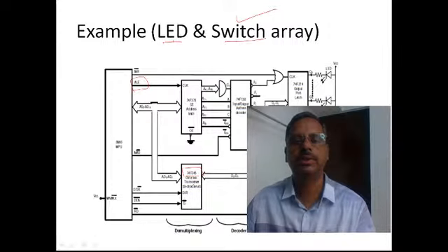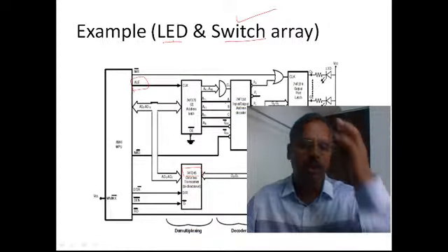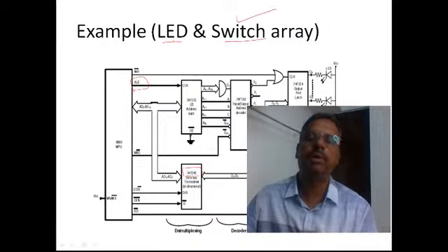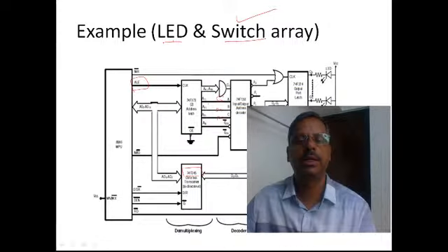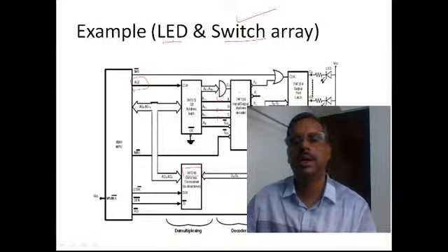74245 is basically a data bus buffer, a transceiver. Okay, so it has been taken here, and 74138 has been taken here. This diagram is not actually using our idea. This only tells how 74138 can be used, where A, B, C is an alternate name for S0, S1 and S2. The selection lines are connected here, and then the G2A bar, G2B bar and G signals are connected here. We will discuss this in our next class. Now you concentrate only on these switches.